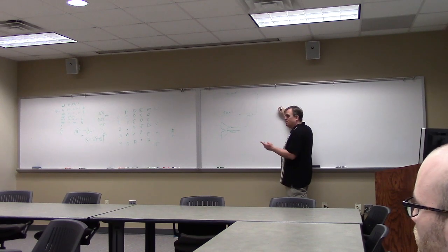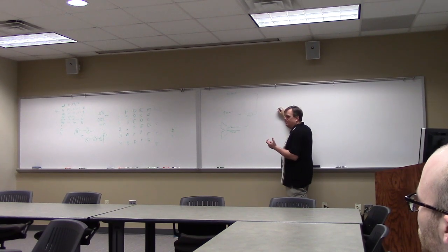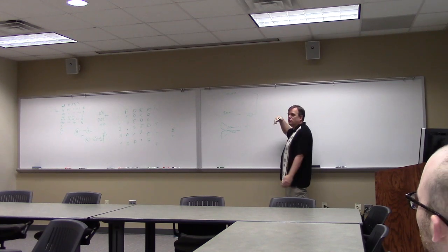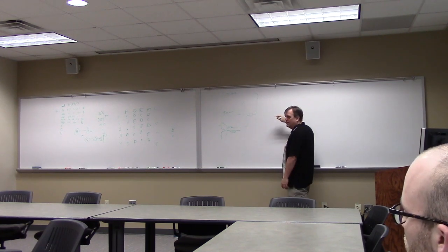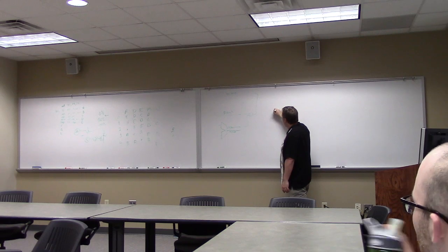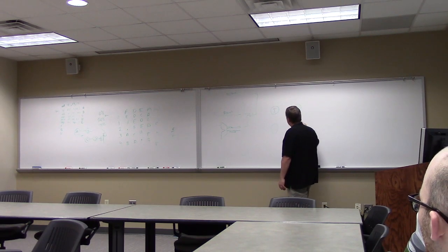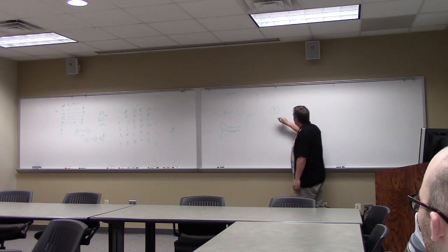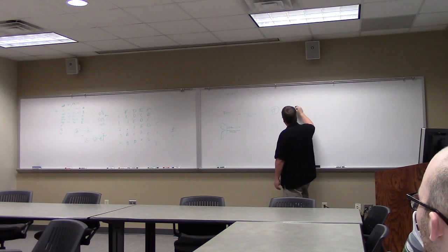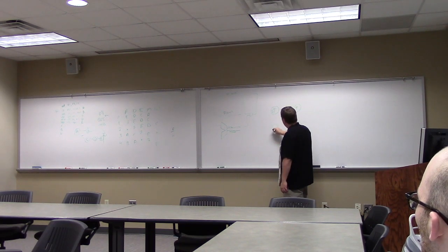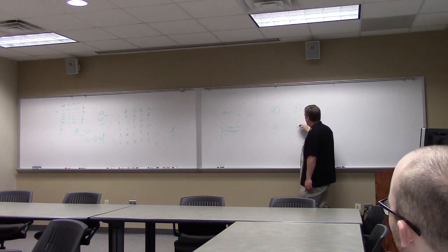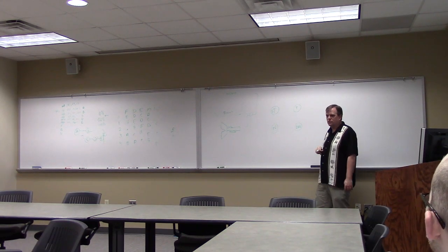So a branch predictor builds a small little finite automaton. Let's consider a small one, just a 2-bit one. This is probably the most common size. We take 2 bits, which means I've got 4 states. So I've got definitely taken, probably taken, probably not taken, definitely not taken. So these are my states.